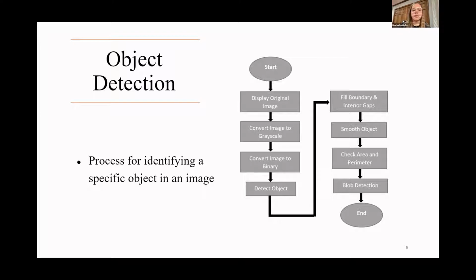We continued by detecting the object using MATLAB's edge function, which finds the boundaries of an object by finding the discontinuities in brightness. In order to fill the boundary gaps, we use the Dilate function and use the Fill function to fill any gaps that were left in the image. At this point, there were still some leaves being detected on and around the Legos.